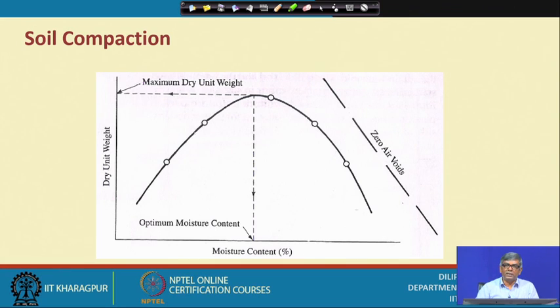As I have mentioned, we cannot add water excessively. So you have to do trials initially. You have to start with some minimum level of water content, maybe 4 to 6%, and compact. For compaction there is a standard procedure. The procedure is given by Standard Proctor, which is the name of the person. He has given the specification for Proctor compaction, what the energy level will be.